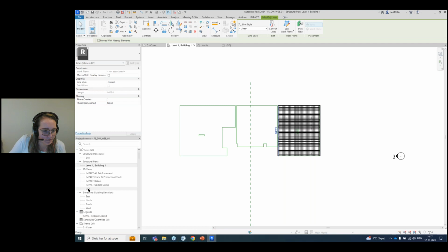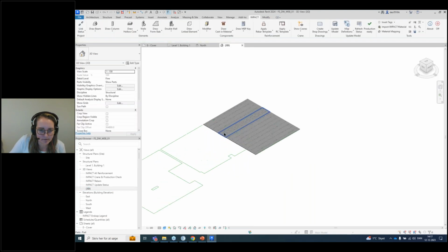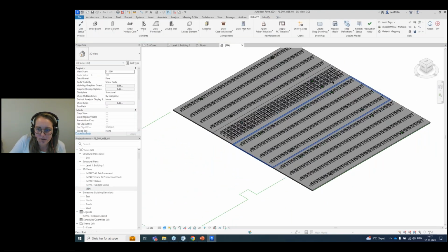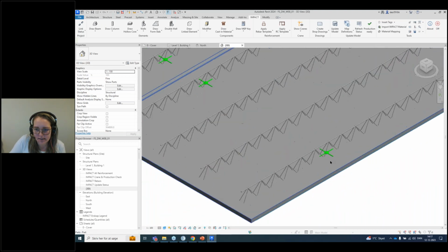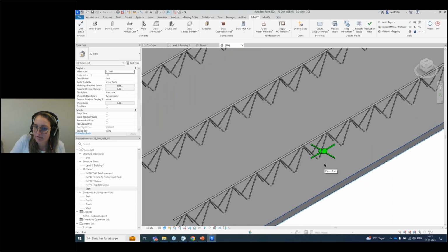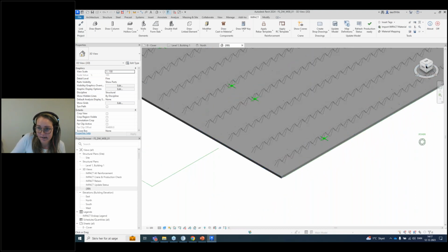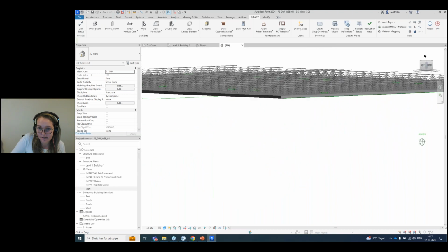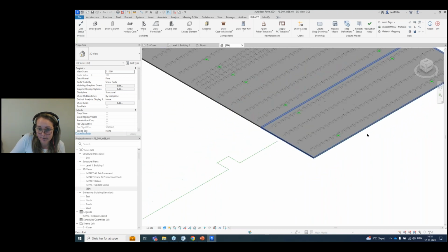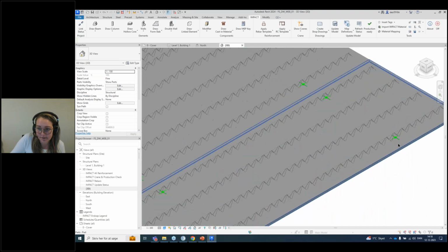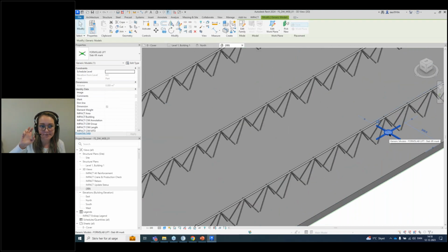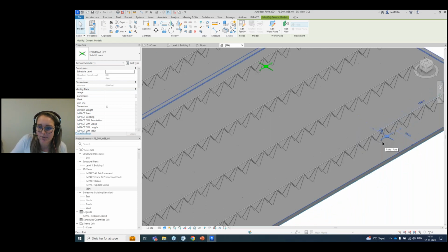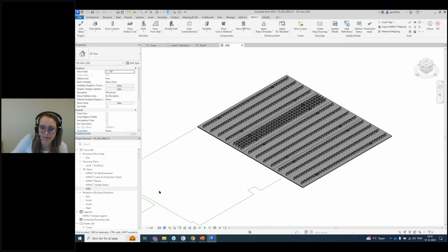I'll jump to the 3D view here and control what we've drawn. Okay, and if you remember, I talked at the start that we don't have lifters, but we're going to lift in the girders, right? Here are the lattice girders, but I want to mark where I'm going to lift. In this case, that's the marker. That's the lift family, which we call a Formslab lift.